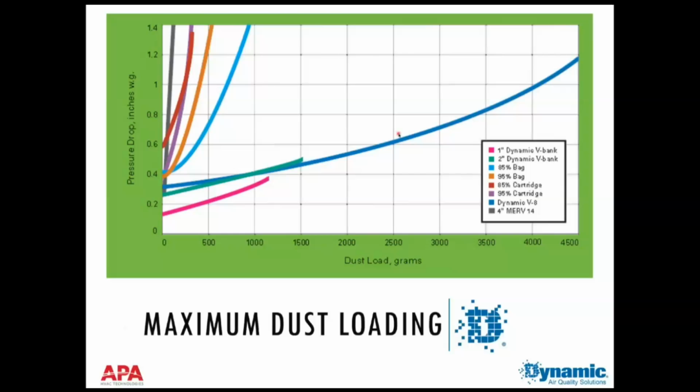So what does that mean? That means that on new construction, instead of designing for this static pressure plus a pre-filter, which gives me a midlife of somewhere up in here, I can design around the V8. Sure, I can change it here, but more likely I'm going to change it at twice the clean static or so, and I still then have a midlife of around 1/2 inch. So that allows me to lower my fan horsepower and fan selections from the get-go.